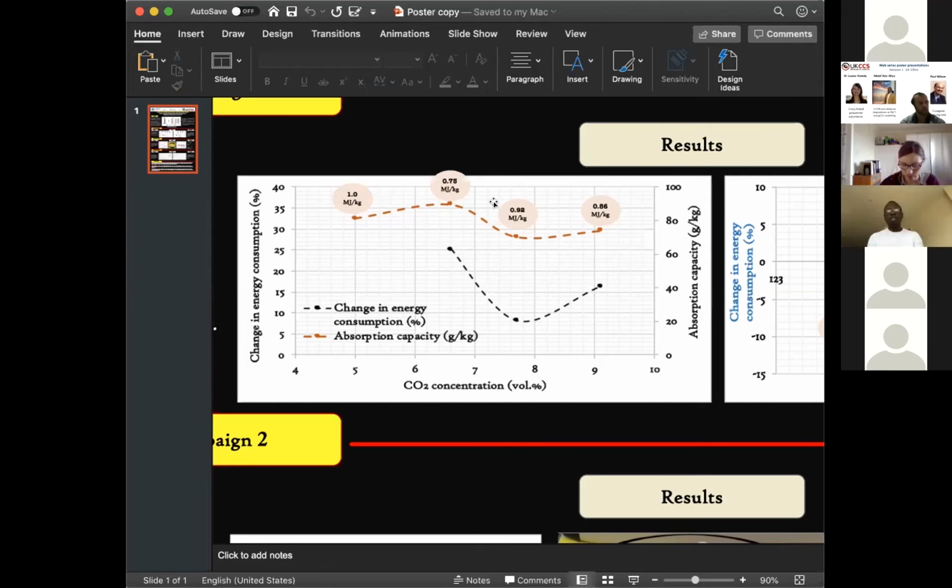If I understood your question, if you're going to retrofit your carbon capture facility to your power plant, the CO2 capture system will have to be designed in line, rather together with the EGR facility. All right, so you can't copy paste an existing, let's say, NGCC post-combustion capture unit and just throw it onto an NGCC with EGR.